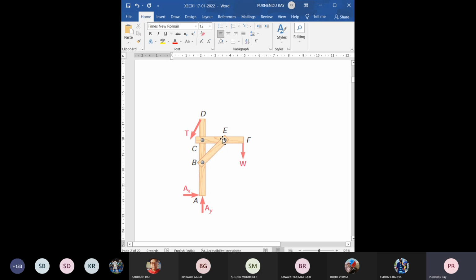Okay, you can try this thing. Extend this line. You take a simple graph paper. From school days, you have many things stored in your house. Okay, so extend this line vertical, extend this line inclined upward, point. You look at this point of intersection, then join this point with this location A and extend this line. That will be the line of action of the resultant.